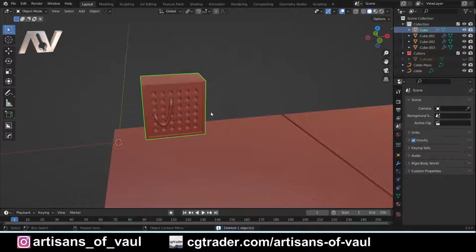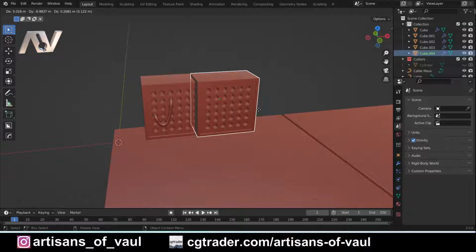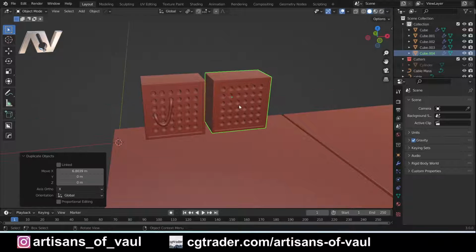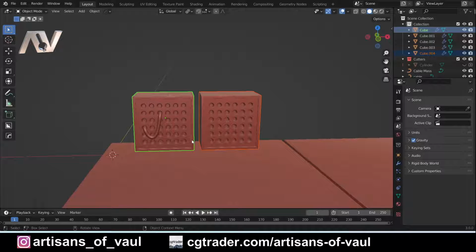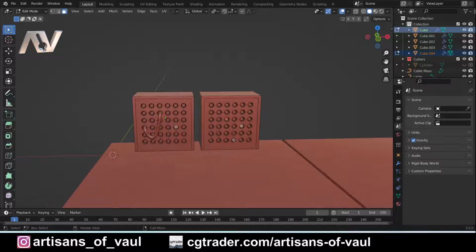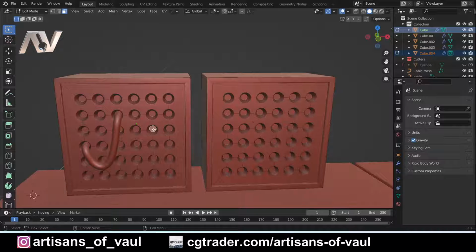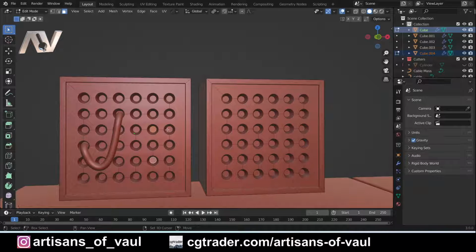I'm going to just duplicate this, so Shift and D. Let's do that in the X direction and put that there. And we're going to do the same thing again, but get this, okay? I'm going to select both the objects, go into face mode, and this time I'm going to select some specific faces that I want. Now, do note I'm going to do 4 here, and I'm going to do the 4 here that I want. Let's do something like that. Okay, and I've found it's generally best to do the same amount either side. It gives you more control.